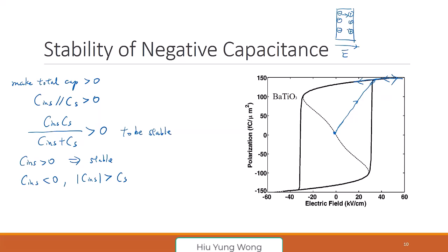That is because the molecular structure for this material, the ferroelectric material, is just like an interlock. We'll look at that later. Once you bend it the other way, it's just like a plastic, a little bit of bulge in this direction. Once you bulge in this direction, when you want to go to another direction, you need to press more than 0. Originally, you think that if I put negative force in this direction, I hope that it will come down. But it doesn't, because it just gets locked there. When my force is large enough, then you will suddenly flip to another direction.